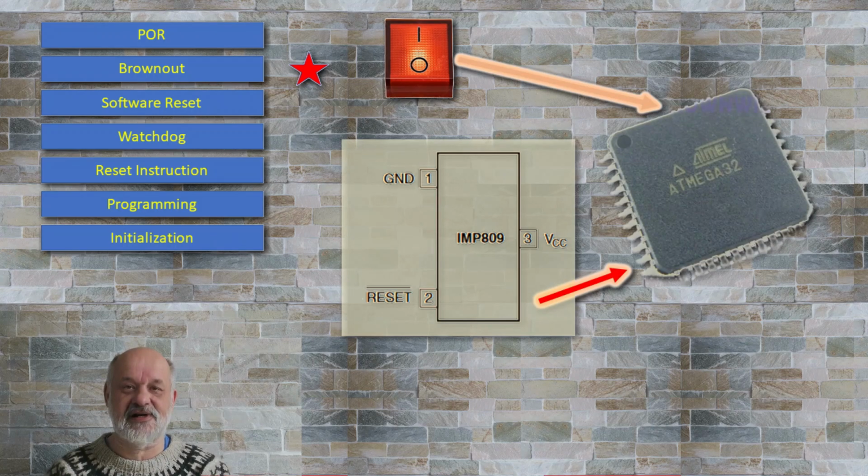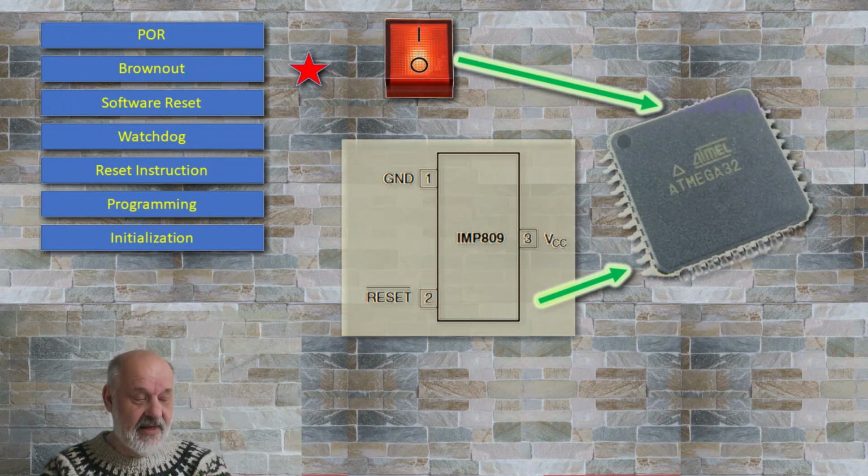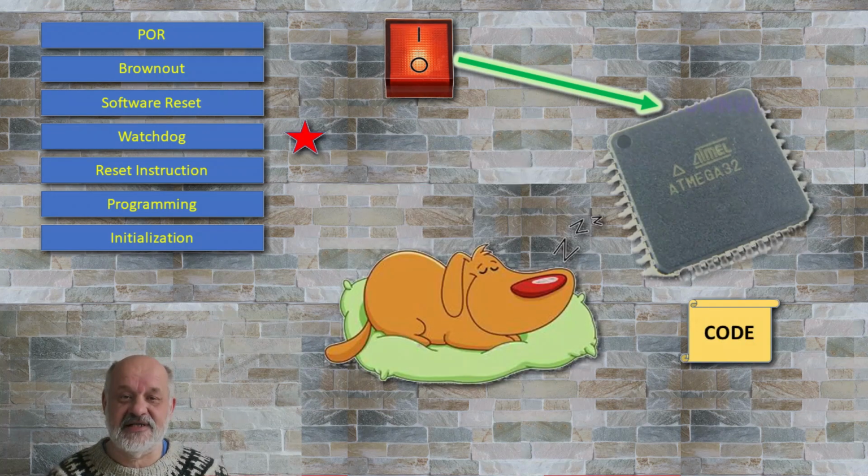Quite many of the internal registers of the microcontroller are random when it starts up like that. Yeah, they are. And then a third kind of reset is an intentional software-driven reset. And this is very different from power-up reset. Quite some of the registers are retained, and when you initialize your system, you should be aware that this kind of reset can also occur.